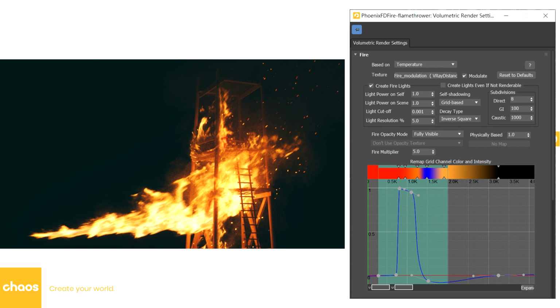After fine-tuning the volumetric settings, we have rendered a new image that showcases the updated visual result. In this image, the color gradient represents different temperature levels, with the core of the fire displaying a subtle blue tint. The curve has been carefully adjusted to maintain detail in the lower temperature regions while avoiding overexposure in the high temperature areas. Moving forward, we will continue using these adjusted volumetric settings throughout the demonstration to ensure a visually appealing and realistic representation of the fire simulation.